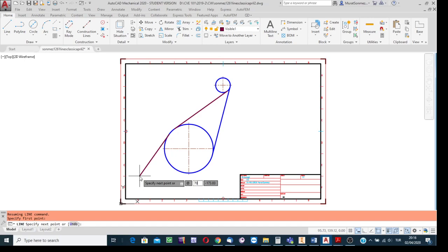Okay, it is the angle key. Click on that key of the keyboard, with the less than, greater than symbols on it. Yes, and now AutoCAD understood that it is the length and the other number is the angle. You see within the last box we have the angle symbol and the degree symbol. It is the third trick.